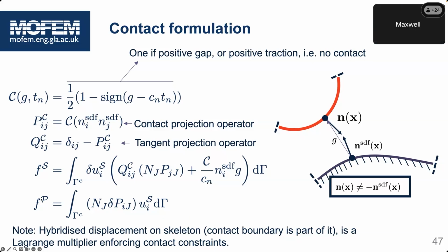we have this consistency equation which tells about the consistency between the gradient of deformation and the approximation of the displacement in L2. And then because we enforce this consistency in the weak sense, automatically the displacement boundary condition is a natural boundary condition. Okay. And then that's fine.